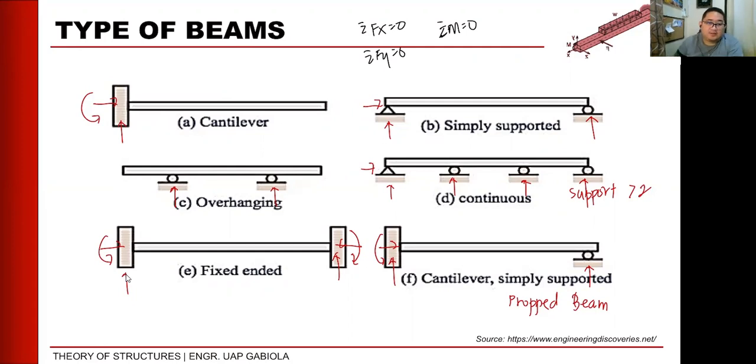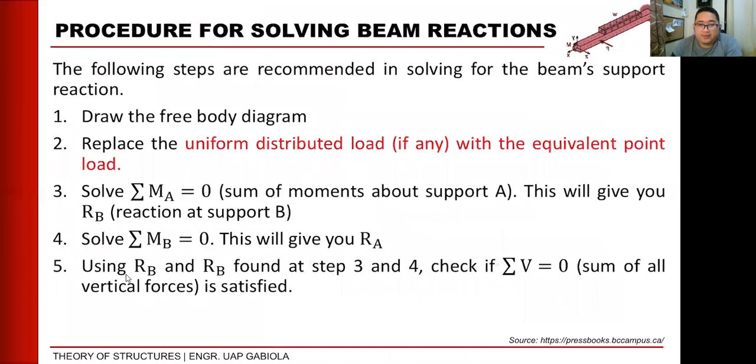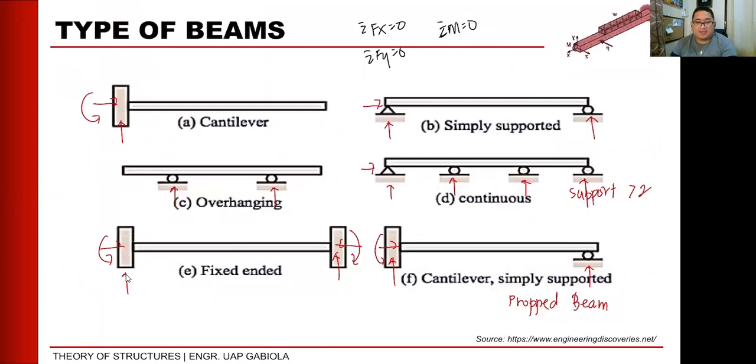Okay? So, ito daw yung steps recommended for solving a beam support reaction. Okay? First one is to draw daw yung free body diagram natin. Okay? So, hopefully last time, napakita na natin to kung paano ginagawa. Pero yung free body diagram natin, kung halimbawa meron tayong beam structure, pwede tayong gumawa ng stick model lang, no? Stick equivalent, wherein doon naka-apply yung reaction forces na na-identify natin sa gantong condition or sa gantong scenario.